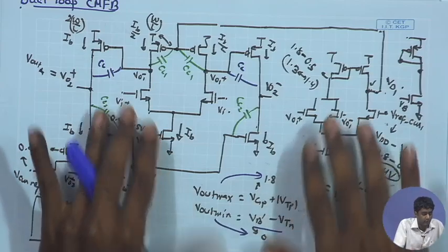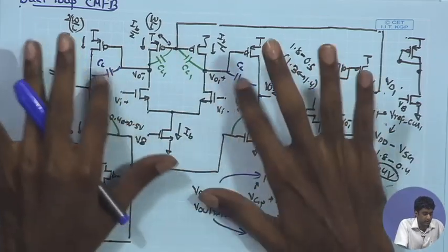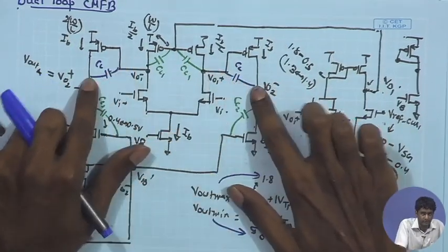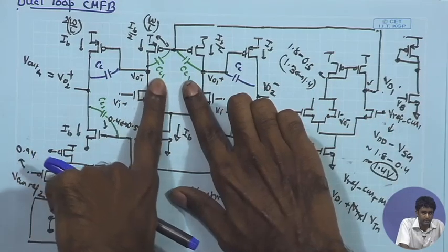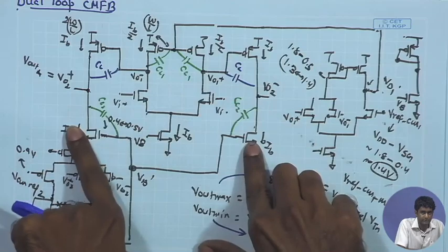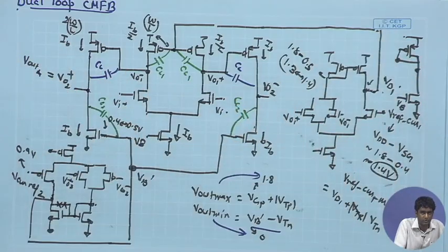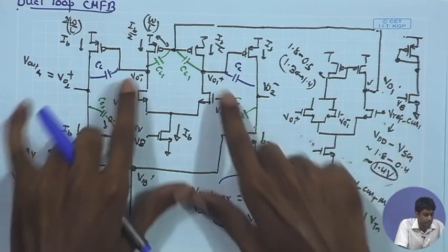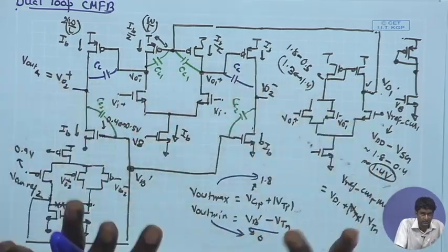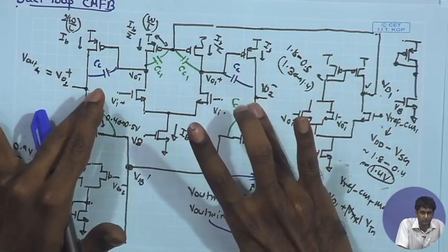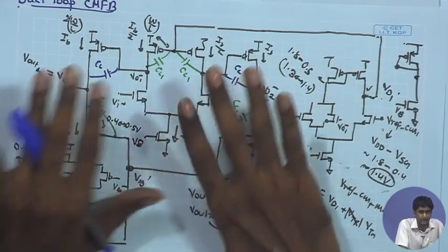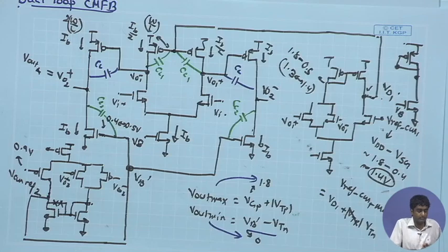Likewise, for the differential compensation, when we are looking at this differential response and counting the effect of CC, what is the effect of the other CC value, CC1 and CC2 on the differential response? That also we need to be aware of, so that while designing we can make sure that the CC1 values and CC values are chosen such that the target differential response for the bandwidth is met and the common mode response is also met.